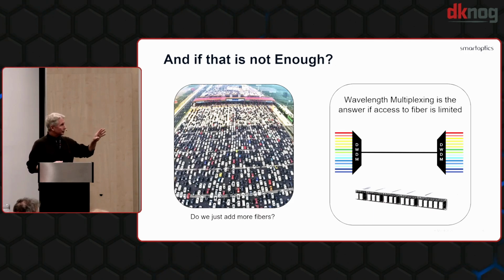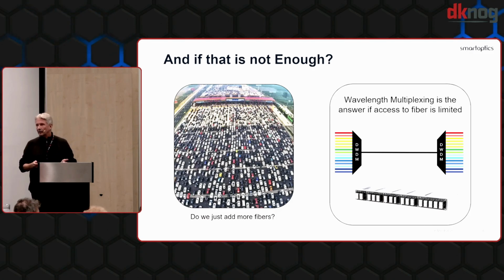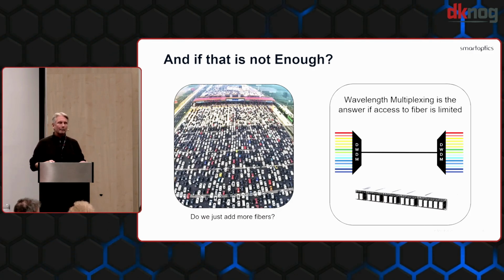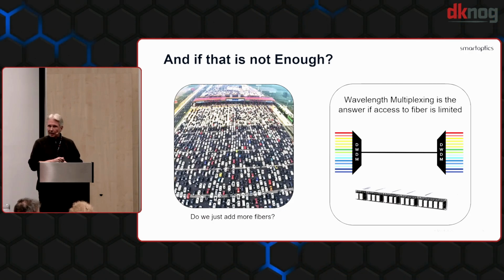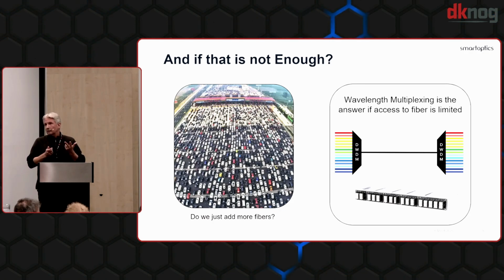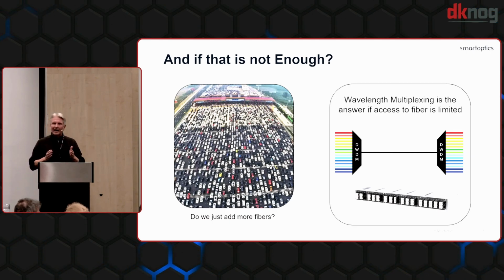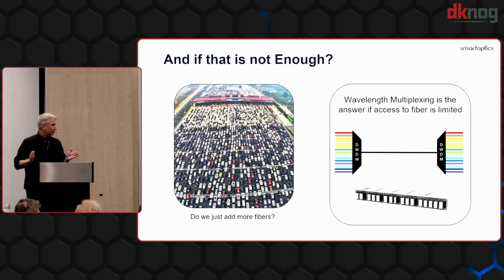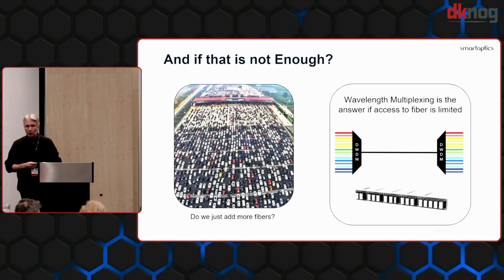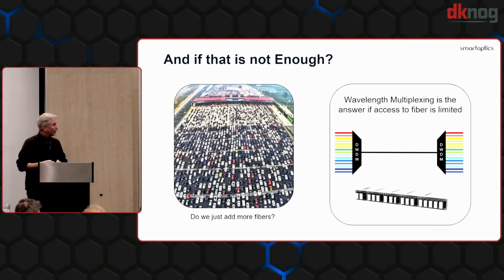In this case now, I show a passive DWDM multiplexer. They can come in different shapes and forms, but typically you have a number of different channels. It can be a 4-channel mux, 8-channel, and a 40-channel, for example. For passive networking, you are typically calculating it up to 40 channels. You normally don't go beyond that because the different filters will also have an inherent or built-in loss in them. The more channels, the more loss, as a general term.